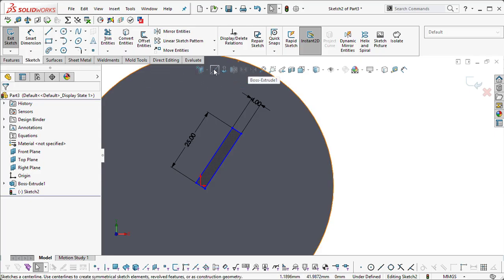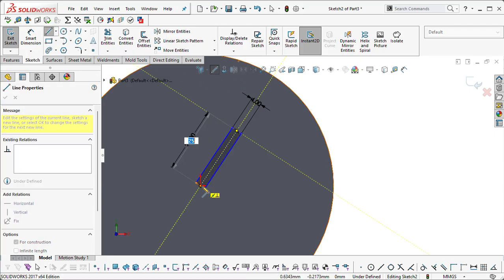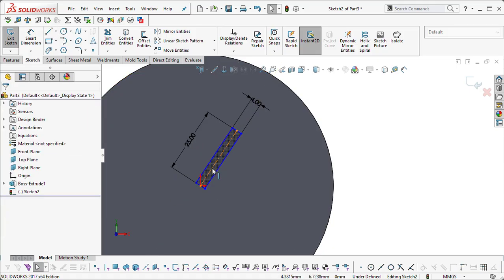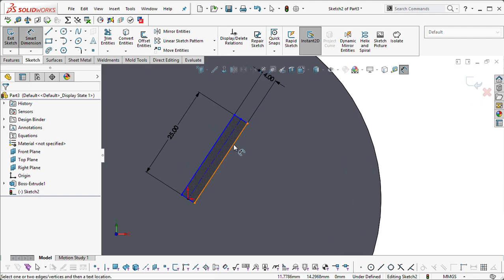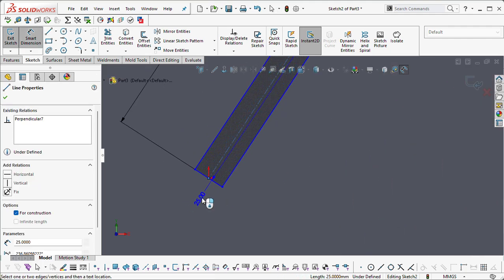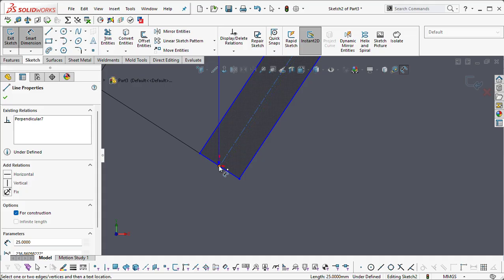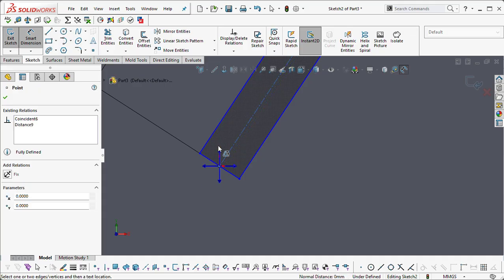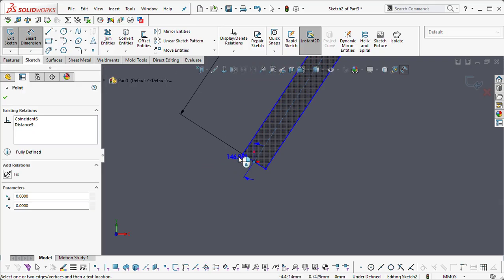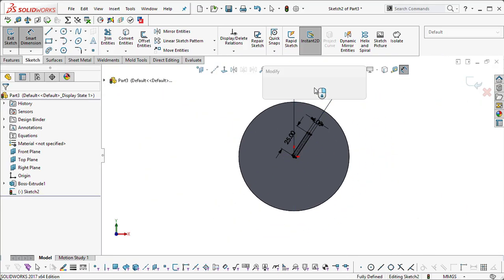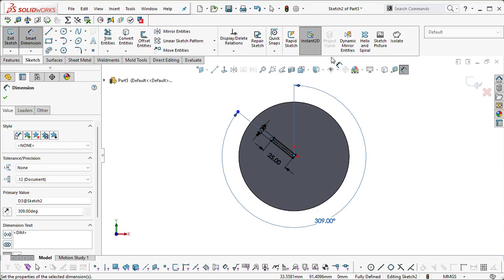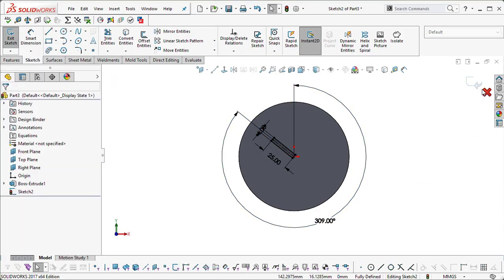I'm going about this in a slightly different order to what I did in class. It'll still work. So let's activate Smart Dimension, click, let go, wait till this button highlights, click, wait till an arrow highlights, click, drag your angle out, and then type something in. It doesn't matter what that is.